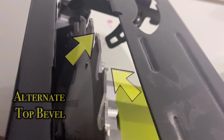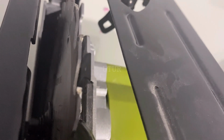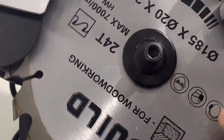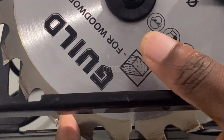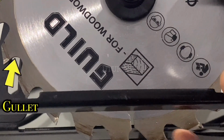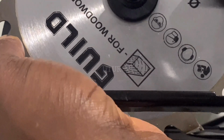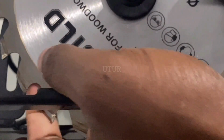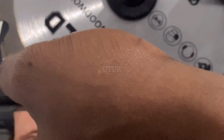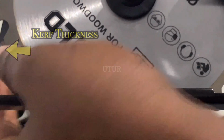The stamped blade doesn't categorically state the hook or rake angle, neither does it state the bevel angle, but we can assume that the alternate top bevel angle is typically anywhere between 10 to 20 degrees. And that's because an alternate top bevel, which is used for all-purpose ripping and cross-cutting, typically has a bevel angle of anywhere between 10 to 20 degrees. The kerf for each tooth is about 2.4mm in thickness.